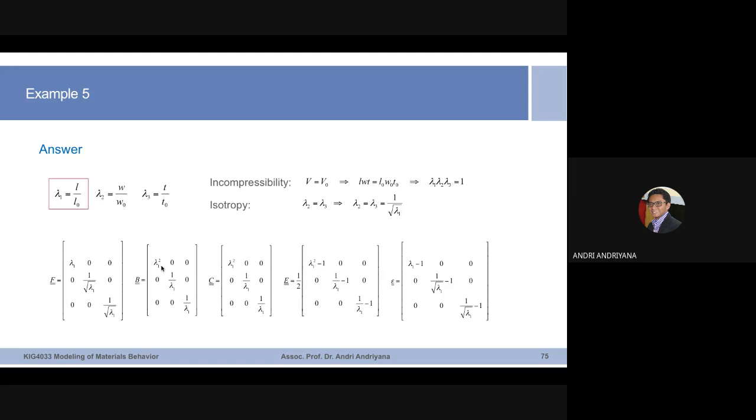So the idea is simply that you want to quantify the shape change. And when you quantify the shape change, you can do it in multiple ways. These are just a few examples commonly used in continuum mechanics that will be used for our purpose next week. Again, to go into the detail, because, for instance, F transforms line elements from before to after. B later will give you information about the length of the line elements. Not only the line element itself, but the length, for instance. So you need to read in the continuum mechanics. That is something that I will not discuss in detail here.